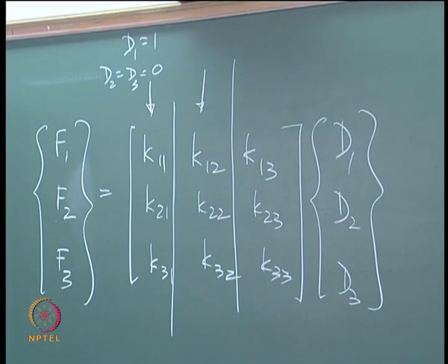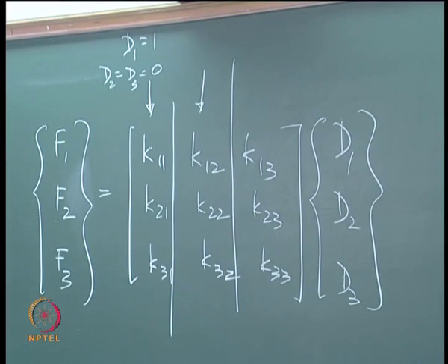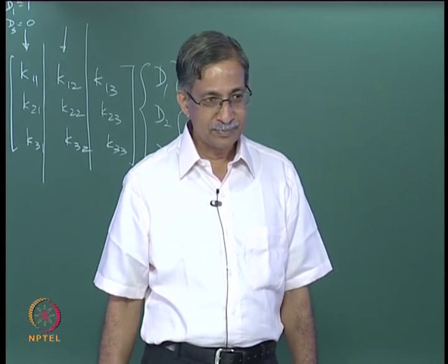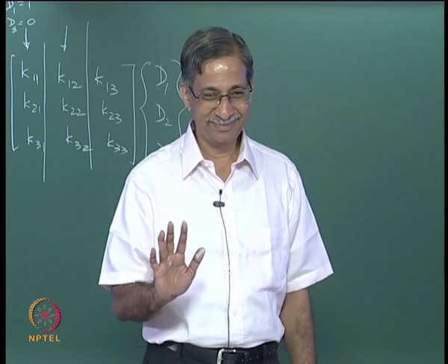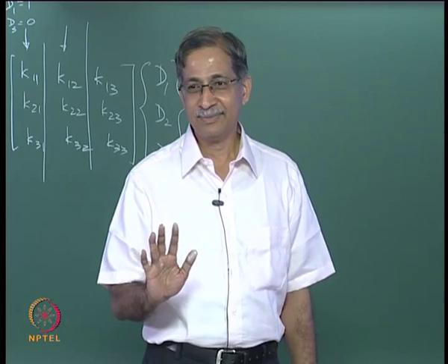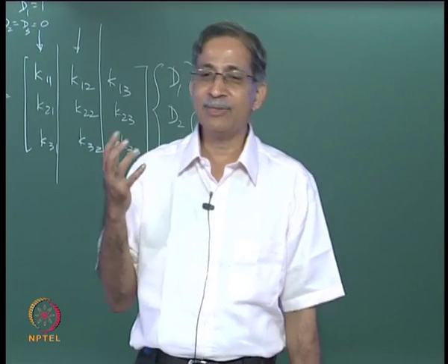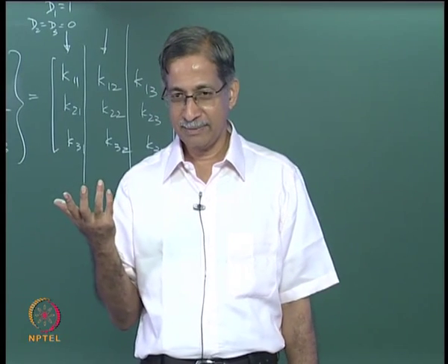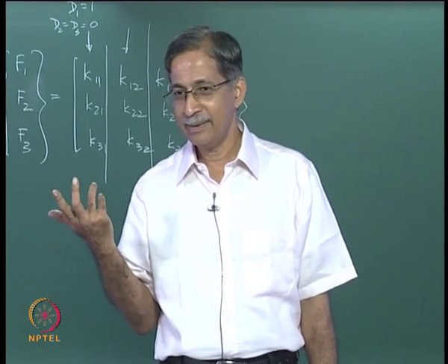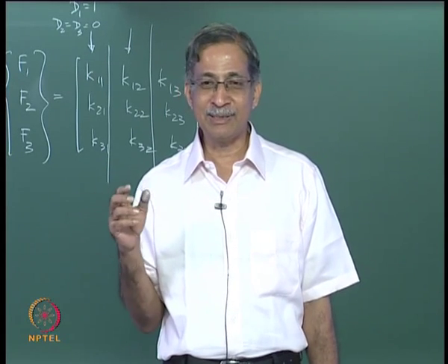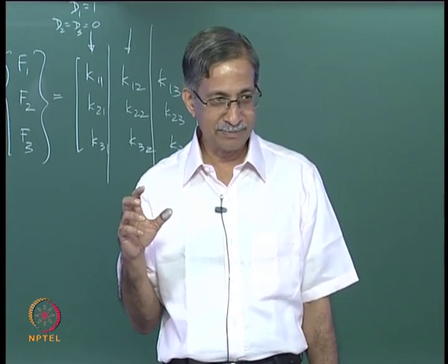Okay, let's look at this. What is the physical meaning of K11? Displacement at 1 causes a force at 1. When you hear of stiffness, you are reminded of a spring constant, right? So a spring stiffness is force per unit deflection.